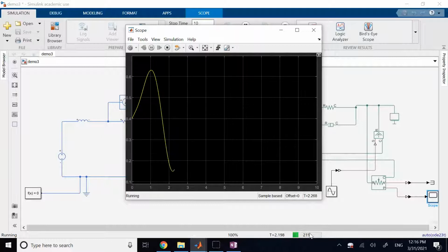And you clearly can see that here I specified initial velocity, initial position, right? The spring constant, the mass constant, the damper constant, the external force F(t), everything is provided here, okay? And you clearly can see I can measure position. So here, that's my position.